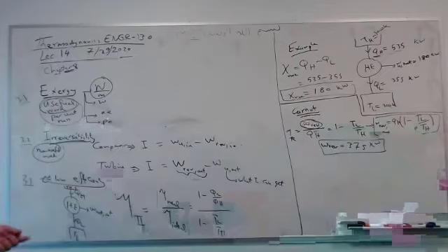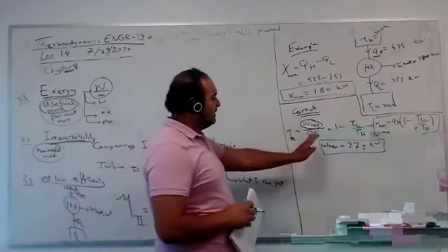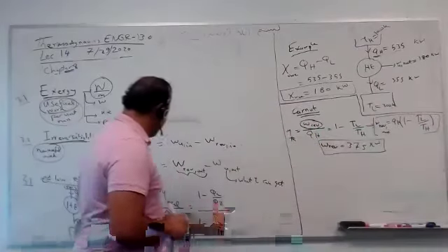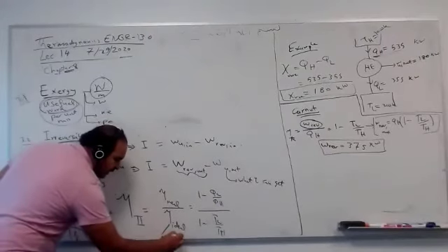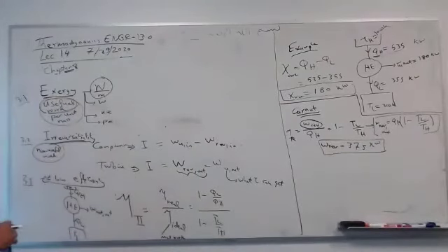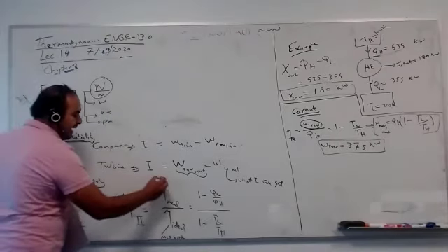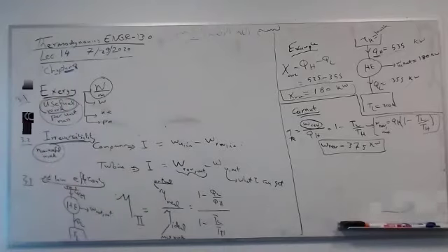So you have T low, you have T high, Q high, you can get the maximum work. Forget about Q low. Does anyone not agree with me on this, guys? You can get the maximum work from this equation. So this is the ideal, the maximum work: Carnot, the reversible, the most efficient cycle. But this is the ideal. What happened? Actual.